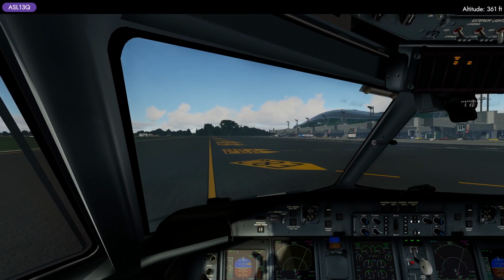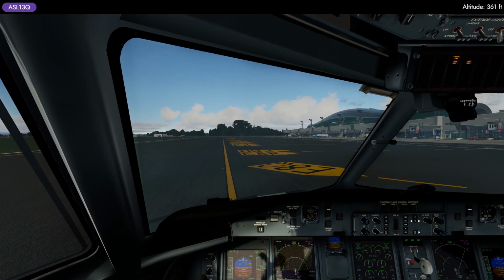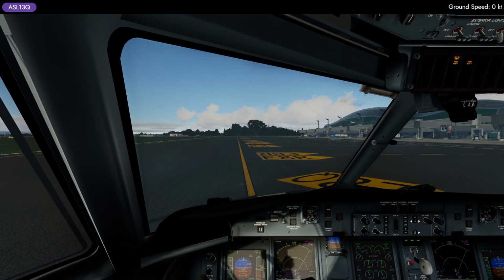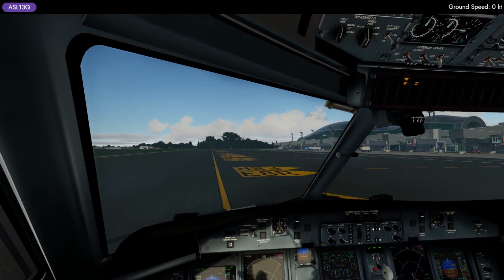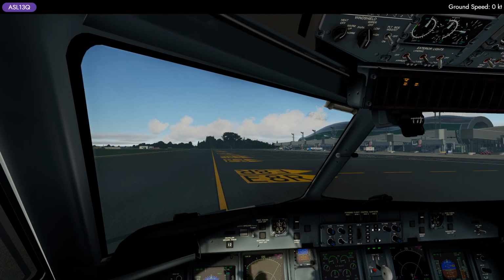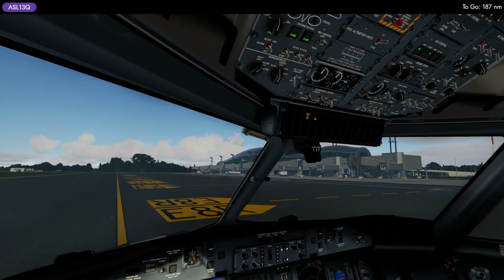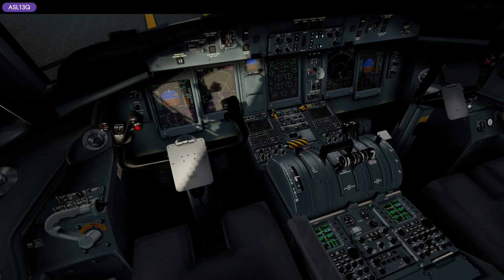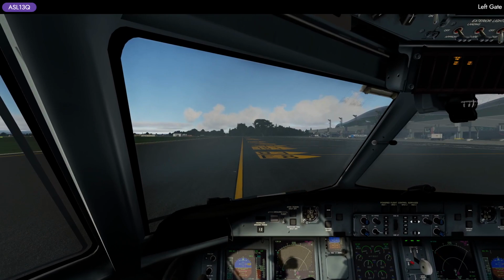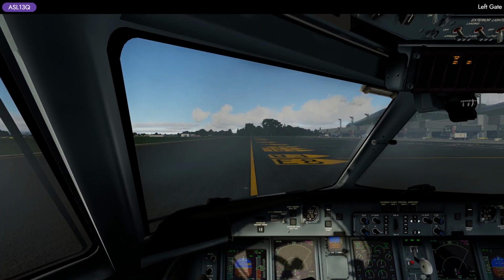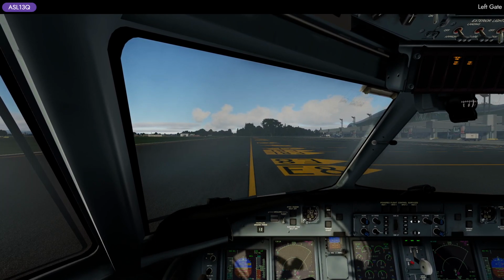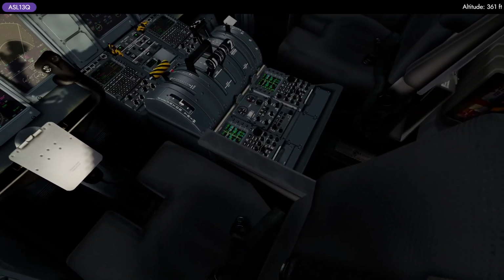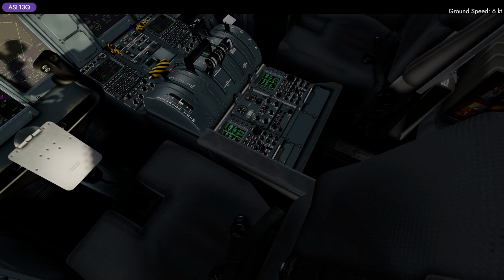We forgot the flaps. Now the misting can be actually solved with warm-up and the pilot side heat, and also flaps 5. So now turn on our weather radar.